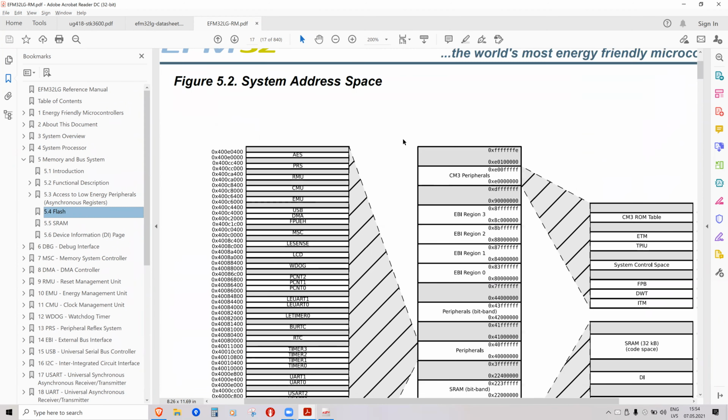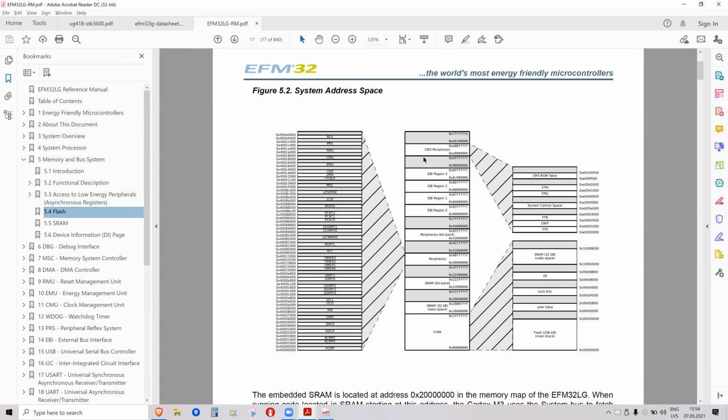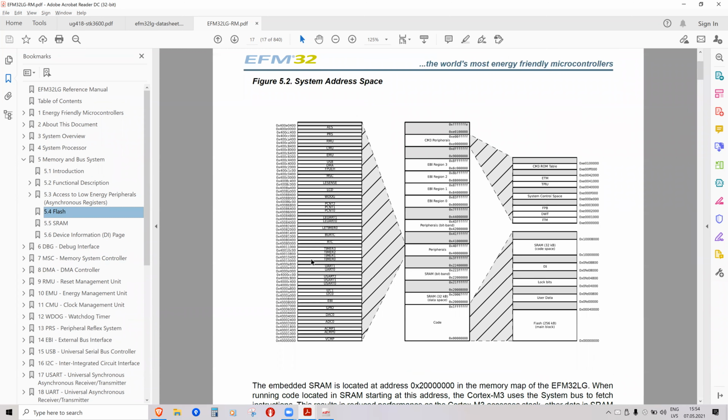Here, so this picture shows the memory organization of our processor. So in the beginning of the memory is your code, then it's random access memory, and then is peripheral control. It is like a location in random access memory at a certain address, and if you write a certain bit at a certain address, something turns on or off or changes settings.